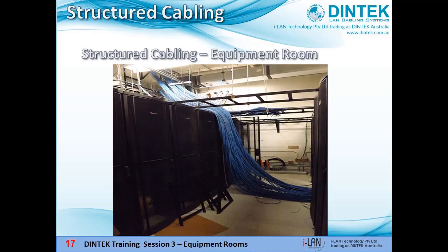The easier way is with the use of an F-set. Here's a quick demonstration of an F-set, which is the easiest way to identify one cable in a bundle of dozens or even hundreds of cables. An F-set has 2 parts, a tone generator which puts an audible tone onto the cable, and a probe which picks up the tone at the other end. The probe makes a noise when it finds the cable.